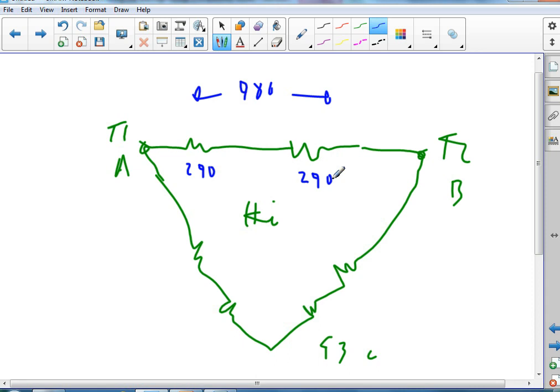On a submarine, all our motors are delta connected, and there are no grounds in the AC system. And in theory, you could grab a bare AC wire and you can't get grounded. You can't get shocked because there's no path to ground. In practice, there is a path to ground. It's a capacitive path caused by the wires being close to each other in our wire runs, and you would in fact die if you did something like that. But it makes it safer, even though it may not be. But the delta wound motor is more efficient than the Y wound motor.